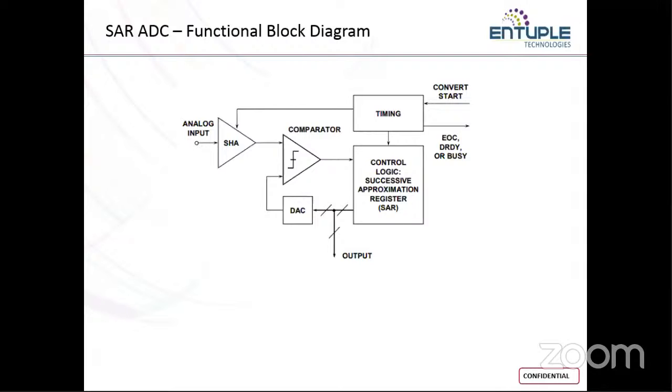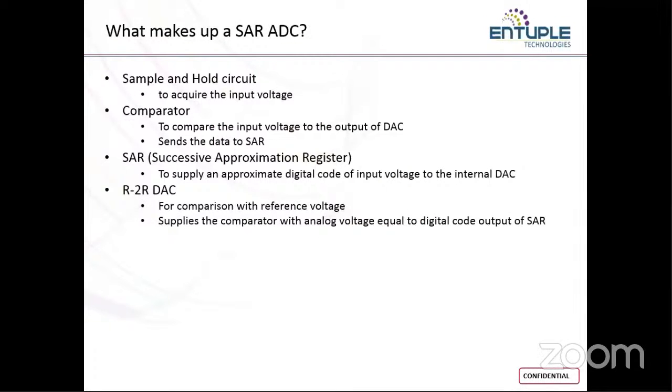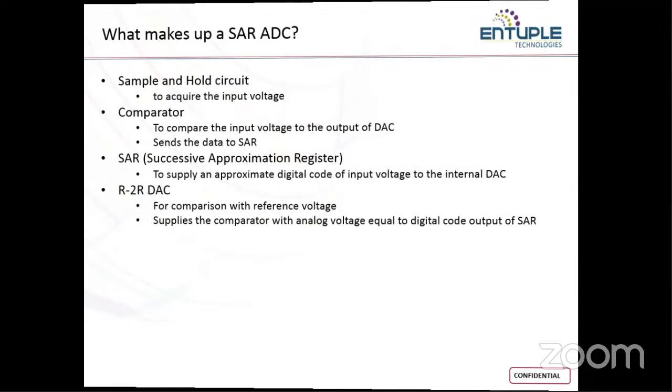And for sample and hold, we had LH398 in terms of ORCAD PSpice, whereas here we made use of a transistor. That's all. And for the digital to analog converter, we made use of a ladder network. The output of the ladder network was given as an input to an operational amplifier again, and the output of that operational amplifier is taken as the output of the digital to analog converter. This is what we had discussed till now.